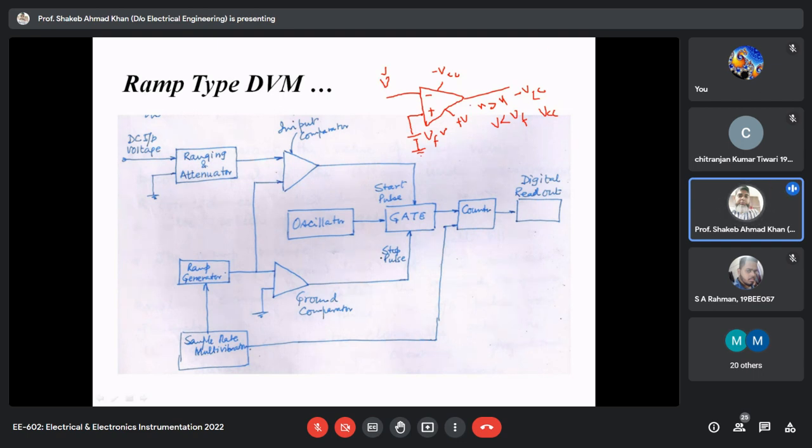So accordingly, suppose an RTD is the sensor, then the circuit will convert this RTD resistance into a voltage, and this voltage is compared with a certain reference. Accordingly we choose the reference and put it either on the inverting terminal or the non-inverting terminal; it is not universal.